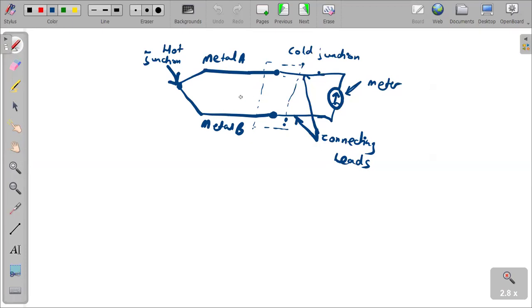Right, and then at one end of the cable, the two conductors are electrically shorted together, right? And this end of the thermocouple cord is the end which is called the hot junction, which is this part that you see here, the one that I'm trying to indicate here. So it is the one we are calling the hot junction, also known as the sensing junction. And it is thermally attached actually to the object to be measured. That's how it is. So I just wanted to add this fact, which helps also to understand how the thermocouple really looks like. Let's just go to the next question.